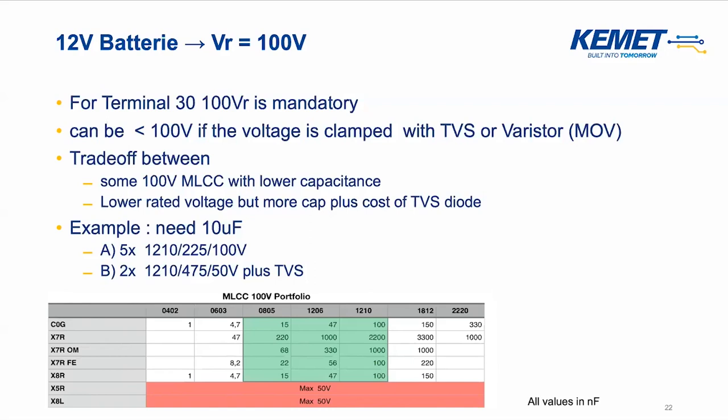So probably you can negotiate a different price, and then you see if the TVS with the lower ceramic volume matters, or you go with the higher ceramic volume and drop off the TVS diode. But that is something where KEMET sales and the FAE team will greatly help you.